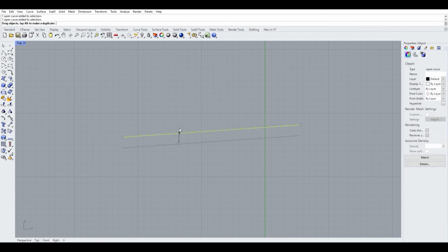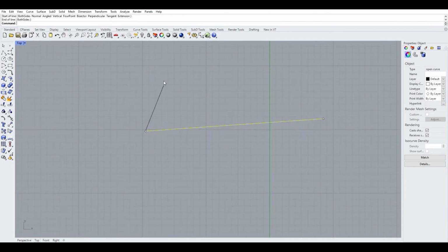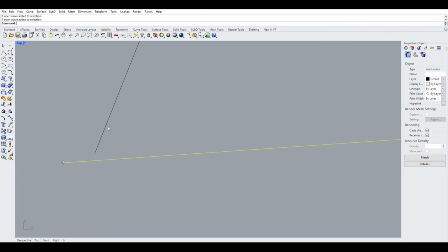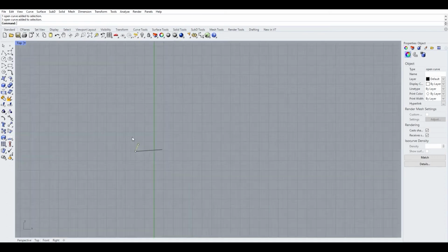But my line is not straight, and I have no specific definition for where I'd like to end or start it. If I wanted to draw a line that connects to that, I can click on the same line tool again, and I can't really find the start. Now, I can zoom in as far as I want, but it's very hard to click and have it start in the same position. So I'm going to zoom in all the way, and you'll see these lines don't actually touch. And that later on will become a very big problem because these objects won't actually interact, which won't allow us to design a valid closed polysurface, which will be very problematic down the line. So I'm going to go ahead and delete those.